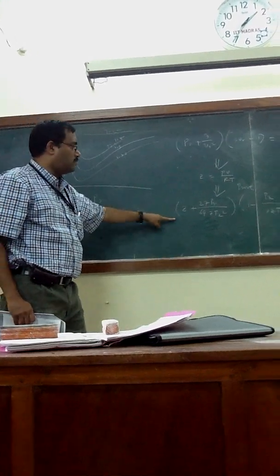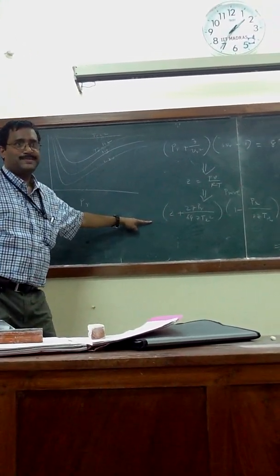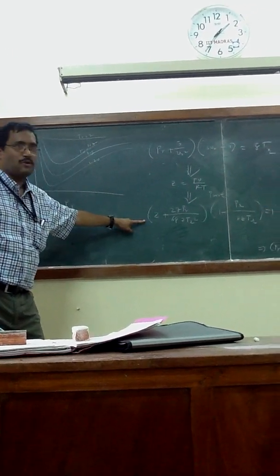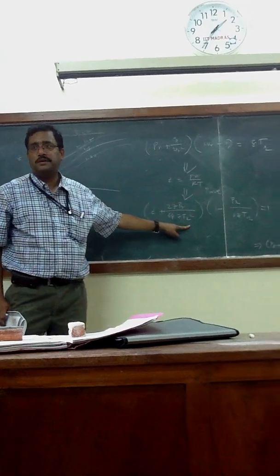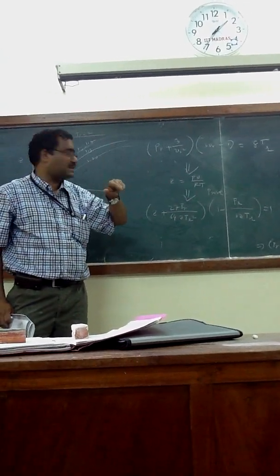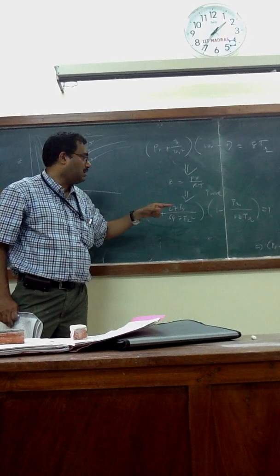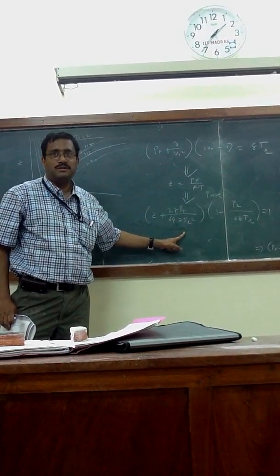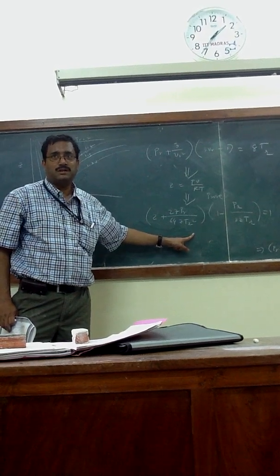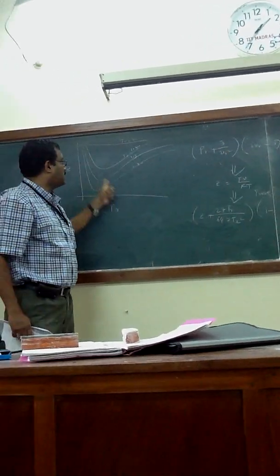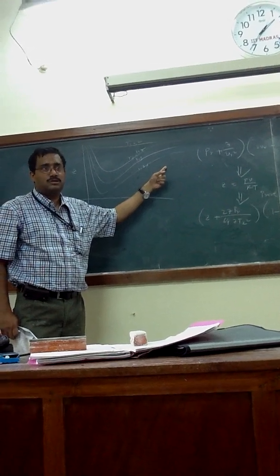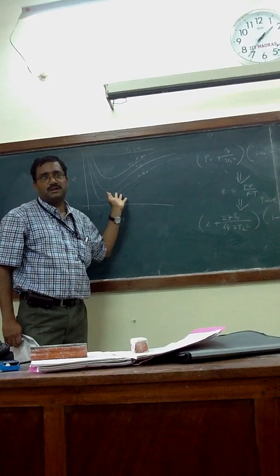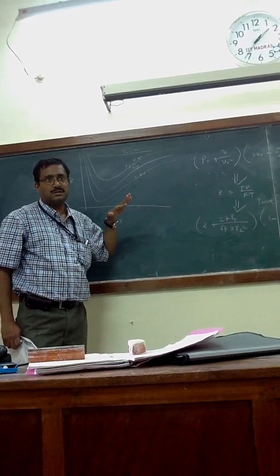From here it is possible to get this diagram. And how to solve this equation by Cardano's method? Now you can see this Z polynomial has all terms in terms of reduced parameters. The problem you solved last time, in terms of Z1, Z2, Z3 and alpha, beta, gamma, they are all in terms of the reduced parameters. So you can solve this equation by Cardano's method, get the MATLAB plot and get this kind of diagram, which is available in the book. So this is the mathematical way to derive the compressibility factor chart. Thanks for your kind attention.